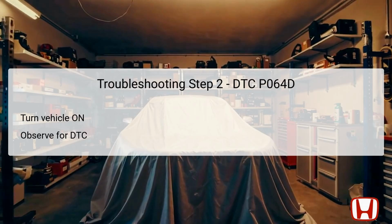After completing the initial step of turning the vehicle off and waiting, the next crucial step is to turn the vehicle to the on mode and observe whether the DTC P064D reappears. This step is essential for determining if the underlying issue is persistent or if it was merely a temporary anomaly.